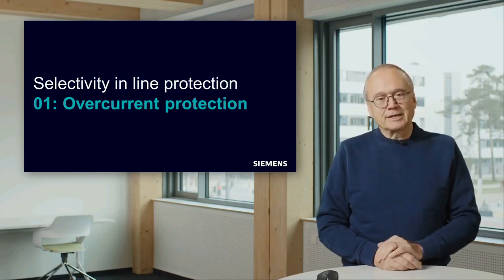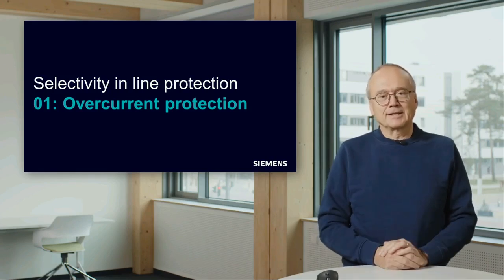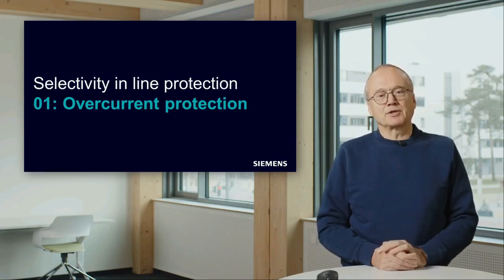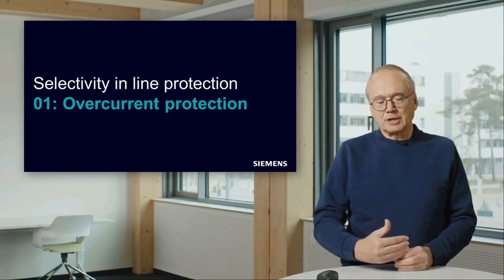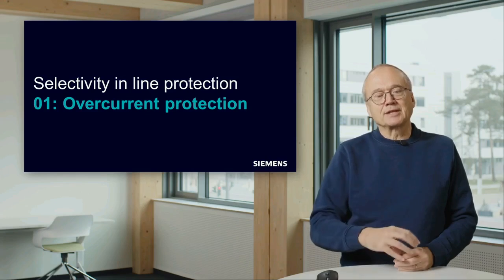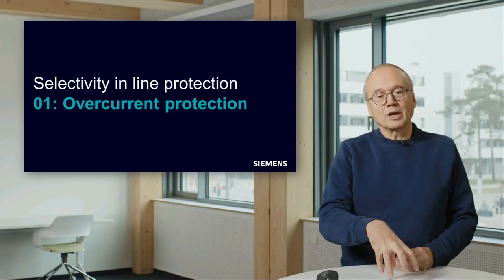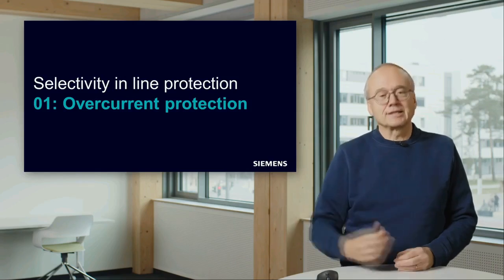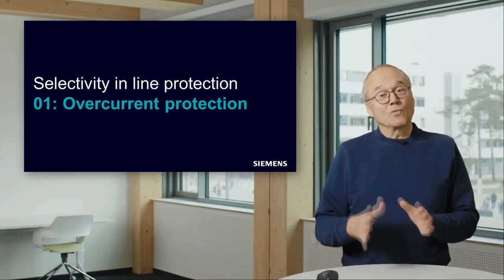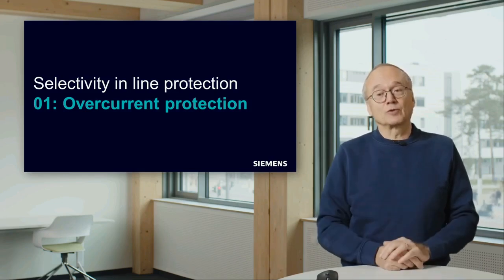If we look at distance protection, at first glance, it looks also pretty simple because distance protection measures the impedance, and by this it can decide, is the short circuit on the own line or cable, or is it on the next line? But we will see later on, it's not that easy. We also have to look into that.